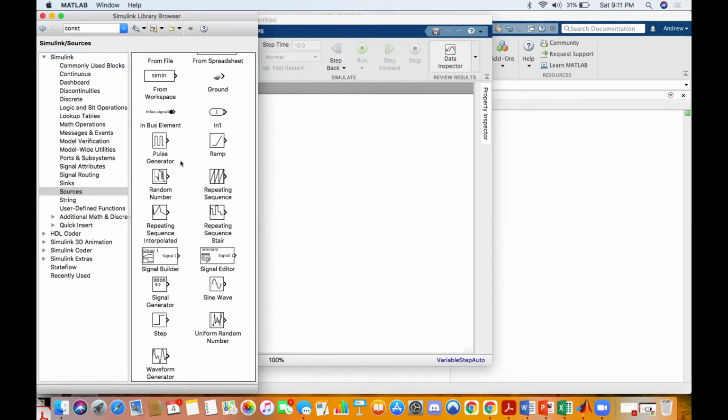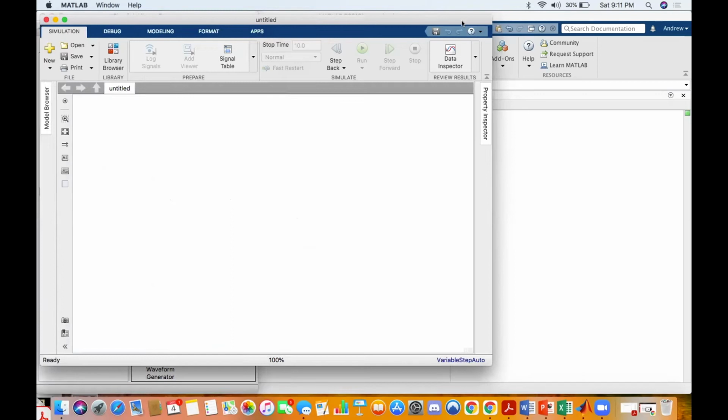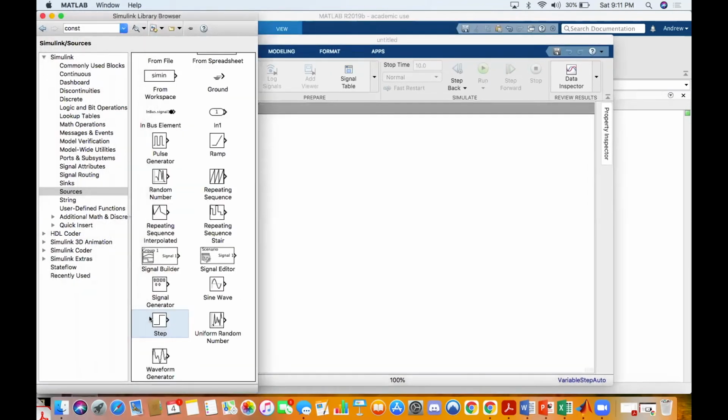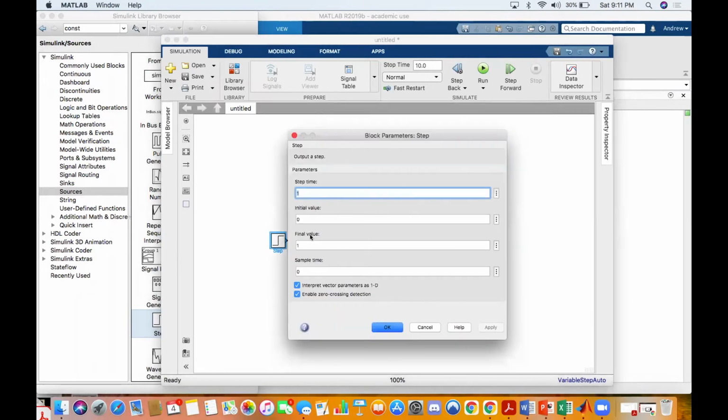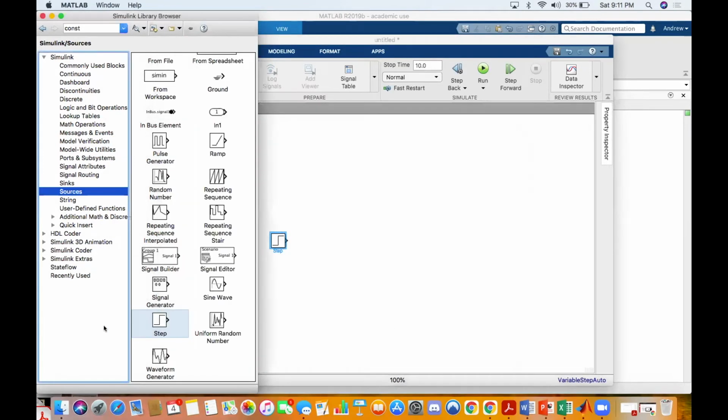And if you scroll down, there's different inputs, including ramp, which is my personal favorite. And so dropping step into the process should result in a step input being added to the flow worksheet. We can drag blocks into the model and choose step inputs and choose different inputs as we go. I personally find it easiest just to use the search bar instead of scrolling through every type of block in Simulink. If you know what you're looking for, this can save you a ton of time during the modeling process.